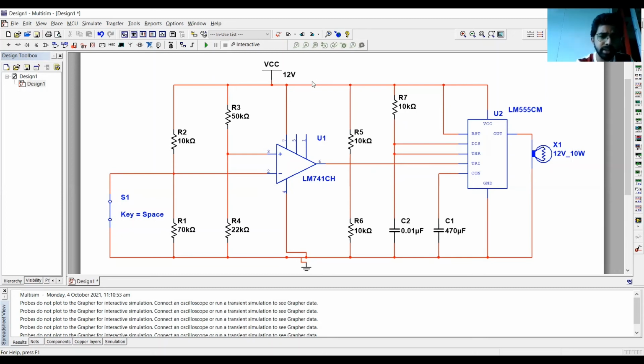So how does this circuit work? This switch is placed on the wall in such a way that the door is opened by pushing it completely towards the wall. The normally closed switch gets opened when the door touches the wall. Okay, we will simulate first.